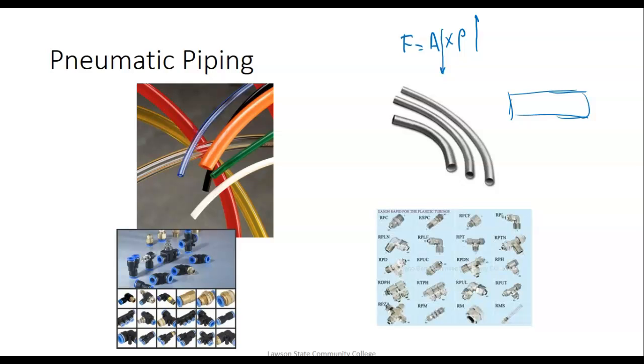Now, if I was going to develop 3,000 pounds of force, and I'm only using 100 psi, that means our actuators would have to be 30 square inches just to do the same work. But they're still doing the same work, right? They're still generating the force, but the big advantage of hydraulics over pneumatics is that it's more compact. The actuators themselves can be a lot smaller, the pistons that actually do the motion and move things around.